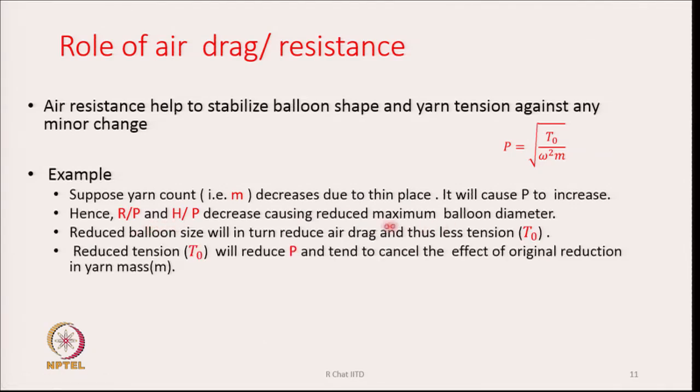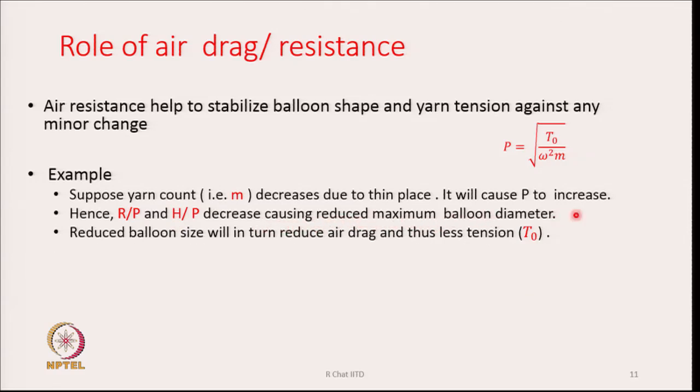Now, what will happen? It will reduce the maximum balloon diameter and reduce balloon size, which will in turn reduce air drag, and thus there will be less tension in the yarn.